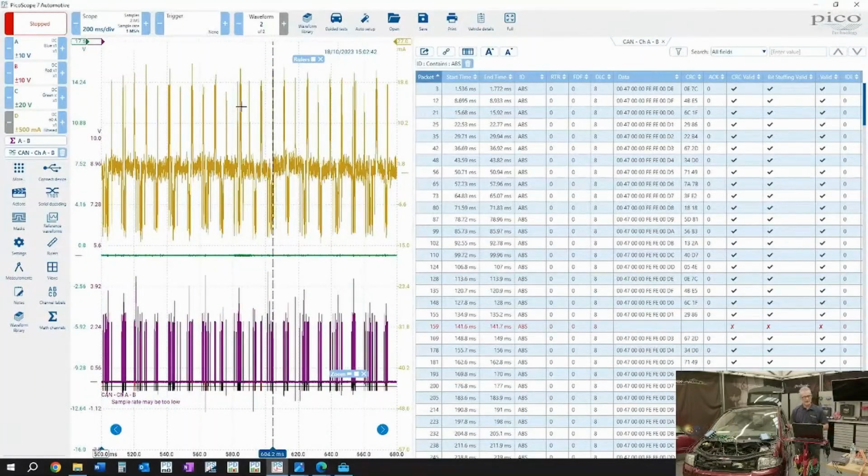So it's a great technique when it comes to actually just seeing if that ECU is online for one, because if it's online, it will be transmitting, and then we'll be able to determine from current flow. Remember, you need to be on a branch for this test. That works well. We're actually rather than on the trunk of the network, on a branch. If that network is going down for whatever reason, it'd be good to monitor the current to that ECU, because if that's the ECU that's responsible, you'll see a peak over and above typical CAN traffic. So it is a powerful tool.